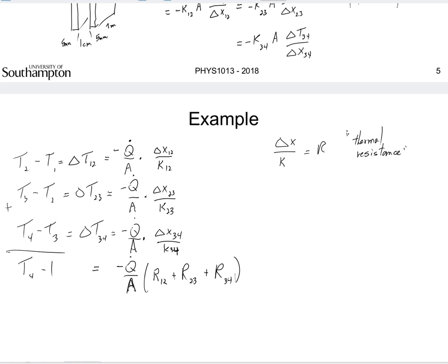In some cases, if you look up tables on the web, if you want to know, for instance, if your house is well isolated, it's a thermal resistance that is going to be given, and then of course what's in there is already the thickness of the material. So they're going to say a brick wall has this thermal resistance, but of course if you put twice the thickness of this brick wall, you double the thermal resistance.